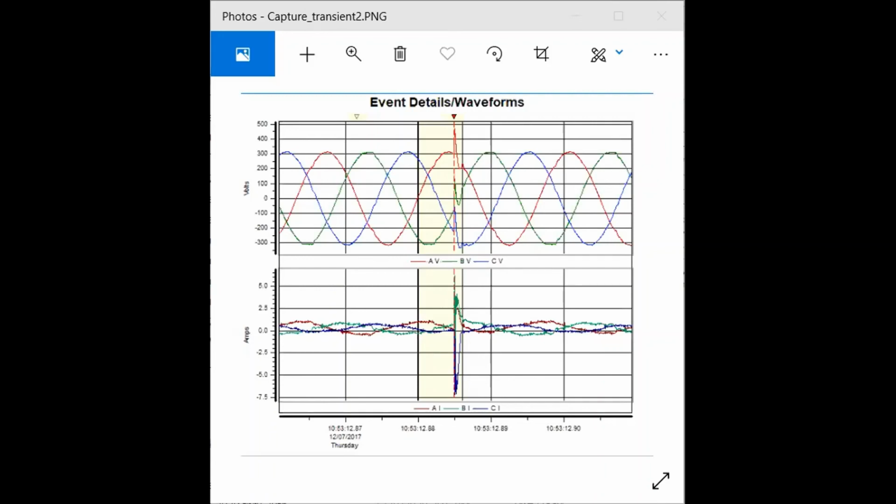I should also add finally, Benjamin, that yes, you made a comment that it's not necessarily harmful. Well, again, it depends on what I explained earlier, but there's something that you should always keep in mind, that you can have what we call incipient events, and these are precursor events. And precursor or incipient events can also be indicators of a pending more significant failure. So, for example, if these waveforms that you're recording are worse in amplitude and recorded more frequently, then you should investigate why that's occurring. Because very often it can be a sign of a more sinister problem waiting to cause downtime and economic impact. So, just keep an eye on that.